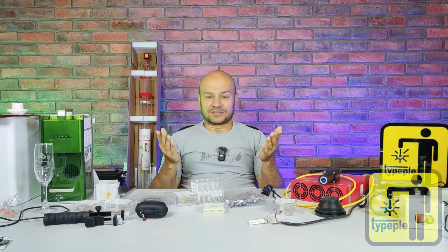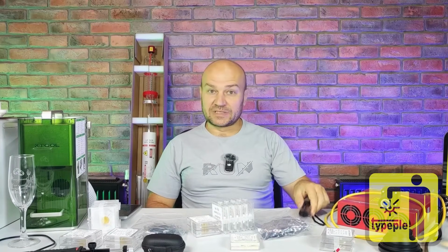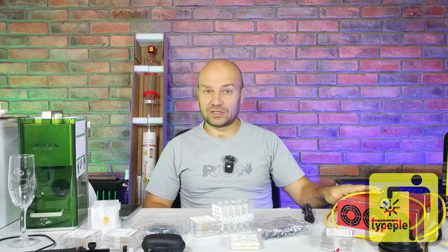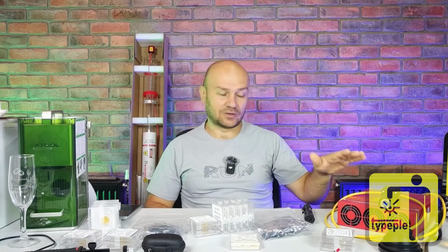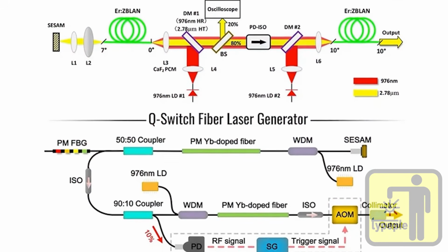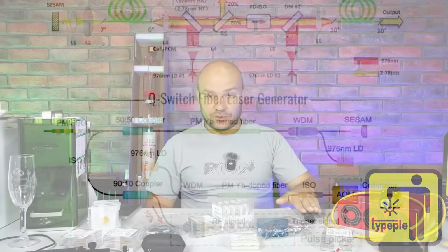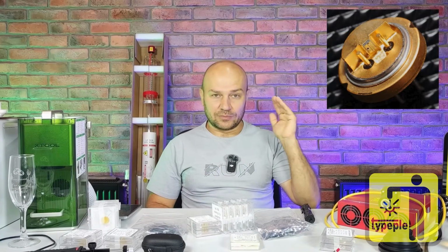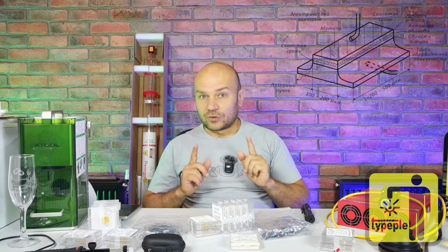As usual, let's get started. First, I want to talk about fiber lasers, specifically semiconductor diode lasers. A fiber or ytterbium laser uses pump diodes, but the actual pumping happens within the fiber optic cable or waveguide. In diode lasers, semiconductors directly emit a photon spectrum that goes straight to the lens to focus the beam.